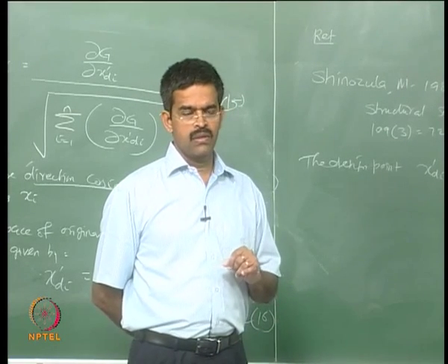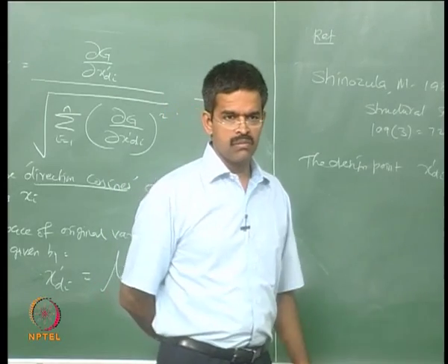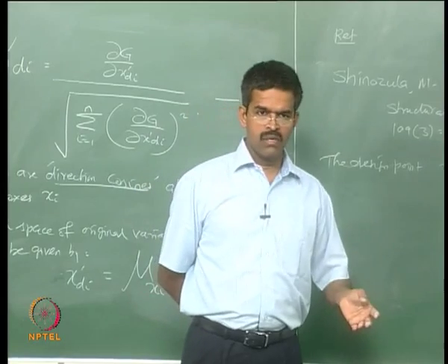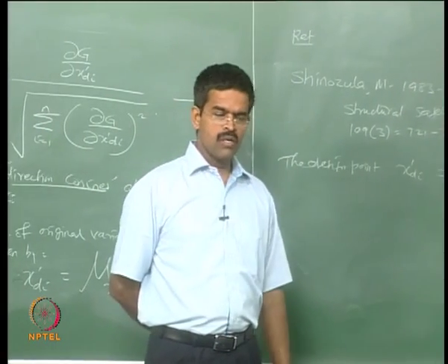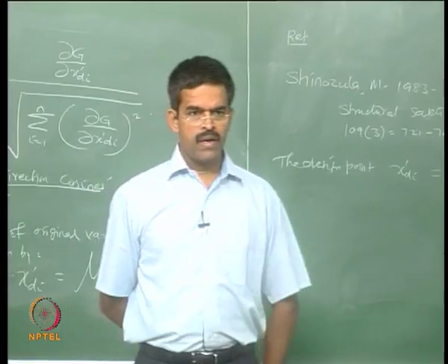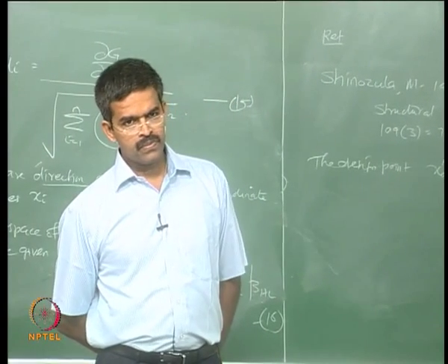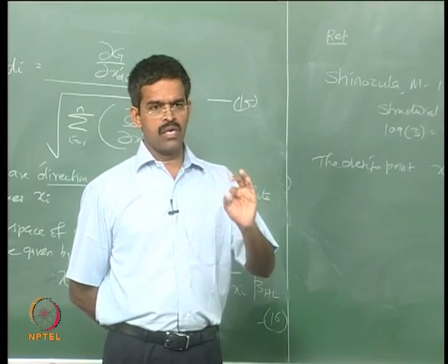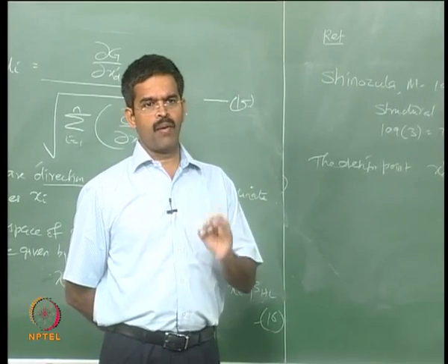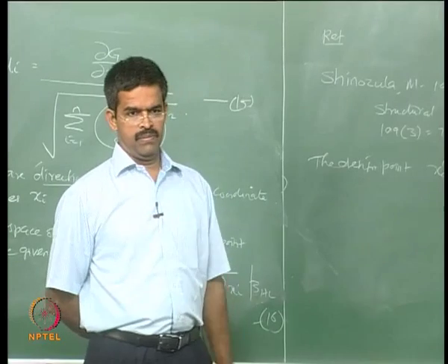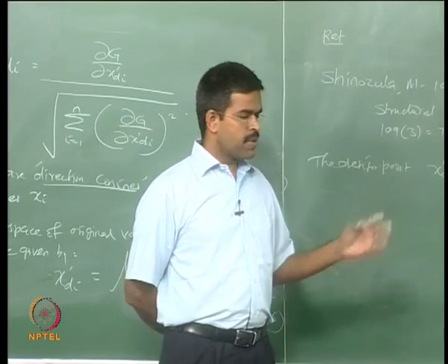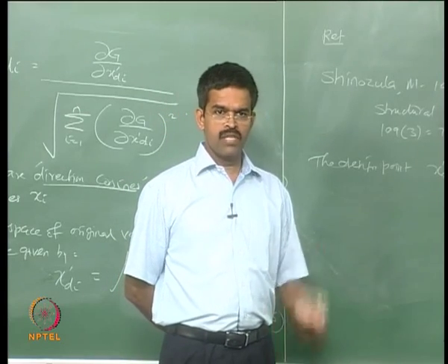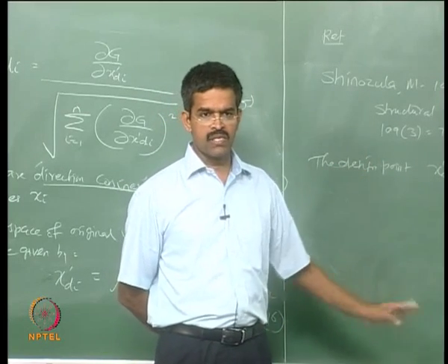Then an advanced method has been suggested by Hasofer-Lind, saying that generalize this function in a different reduced form which has unit standard deviation and zero mean process, and find out the coordinates of the so called design point or the check point or maximum probable point on the limit surface. So, this becomes an optimization problem. You have got to minimize the distance d with respect to the failure function as we have discussed.